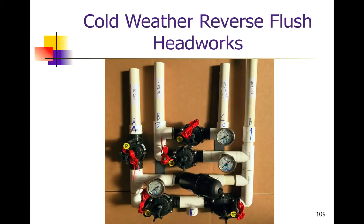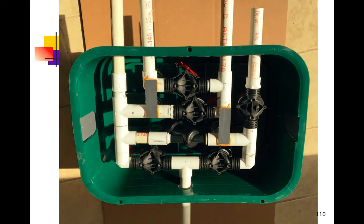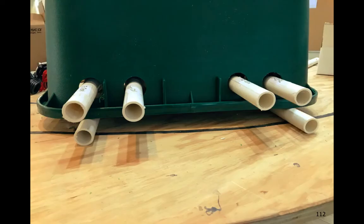Now, if we're going to do the cold weather with the reverse flush headworks, it's the same procedure. We're going to glue everything on the one end, A, B, C, and again B. Remember, always in Eastern Washington, put the cold weather adapter in. The system won't function without it. Again, we put that in the headworks, and then we glue in D last. Now, when we turn it over, again, we have the same instructions on the outlet side.